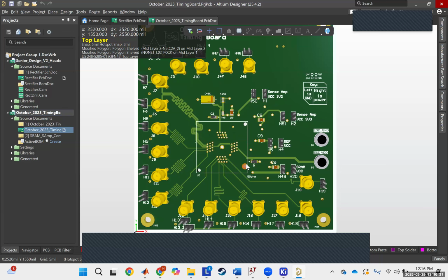So whenever you have these high-speed signals, these fast-moving edges, you'll want to have this link tuning. Sometimes you'll have to have it just to make sure everything reaches there within some tolerance of each other. And that's done by making the lines themselves the same length. Within here, the tolerance is within like 100 mil of each other.